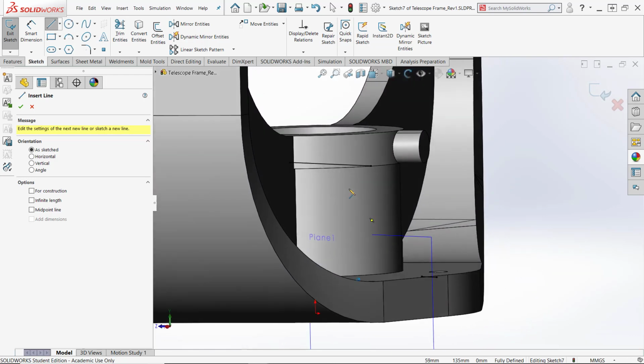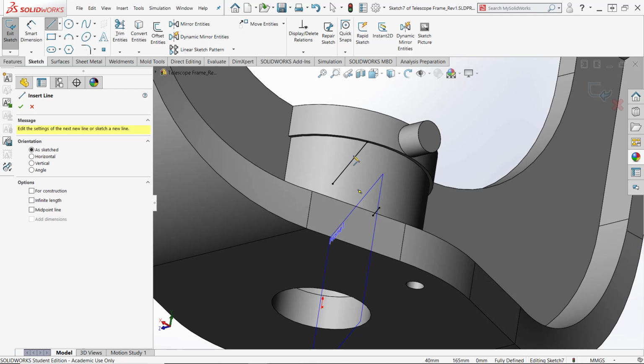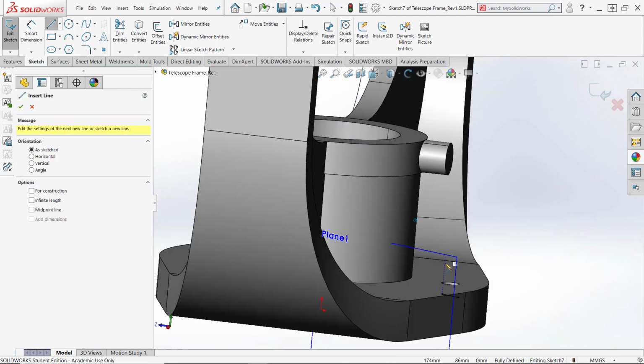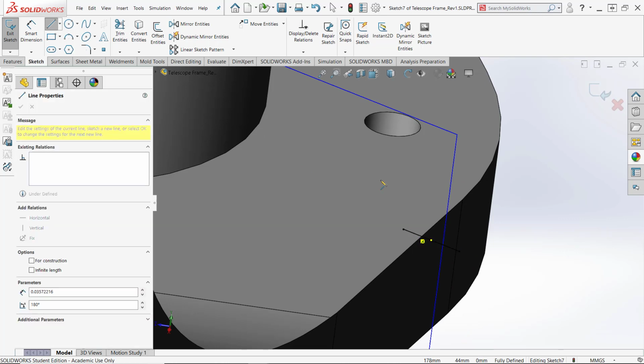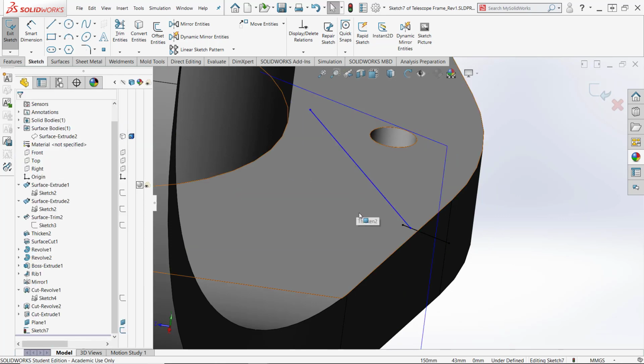You know what, I'm going to take this line out here. We'll put that back in here if we need it. Let's draw a line from this line, and again, be careful you don't get the midpoint of this line, don't get the end point. I'll get that line here someplace about like that, and I'm going to connect the other end of it here in a minute.